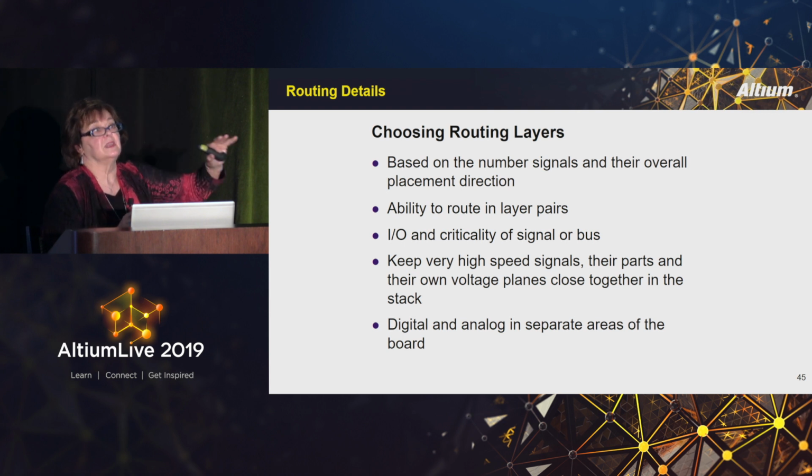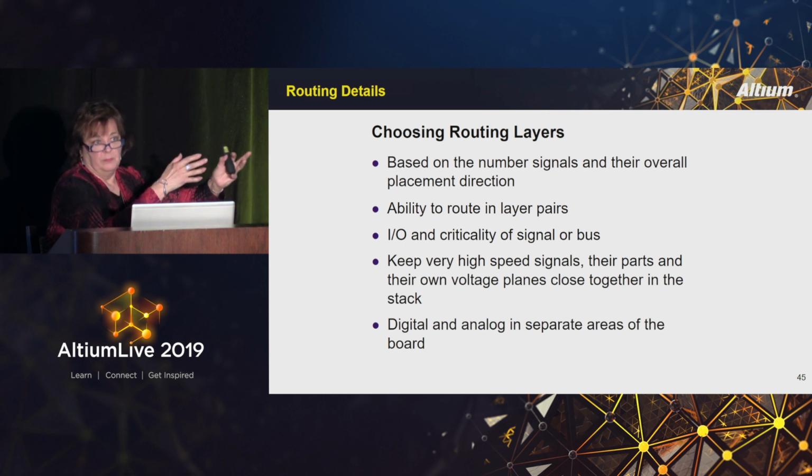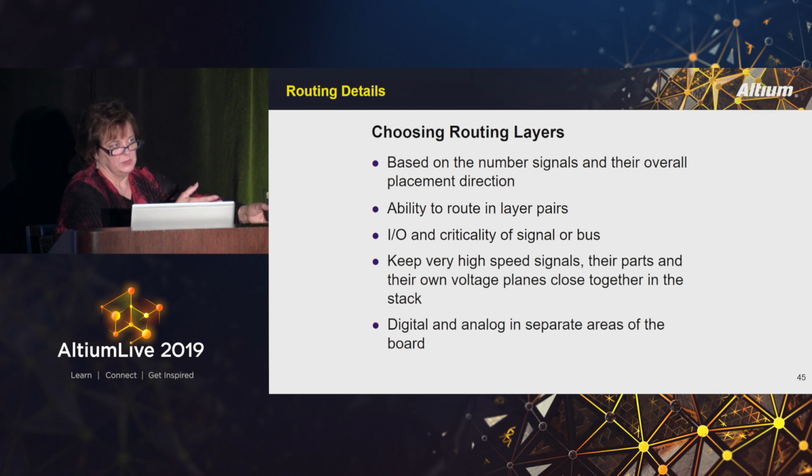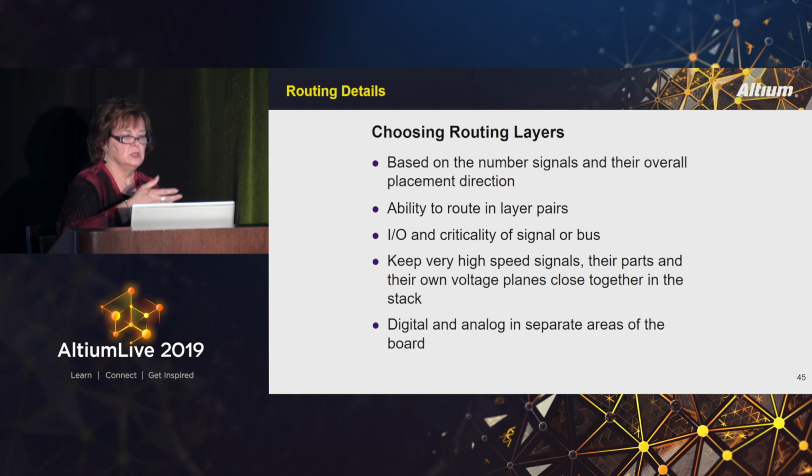You don't want to put anything close to the I/O because the I/O is going to carry any extra energy off the board, probably through a cable, maybe through another connector. But if it goes into a cable, it could very easily become an antenna and spew all that extra energy out into the board next door, into other things that might be nearby. And it can also receive energy. Remember, an antenna sends and or receives energy.